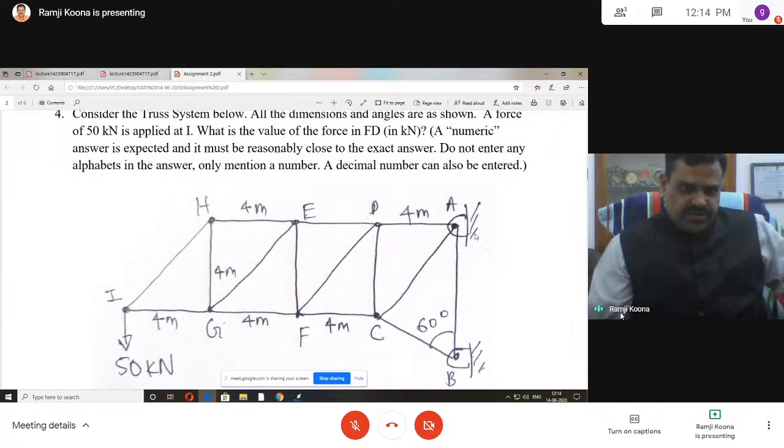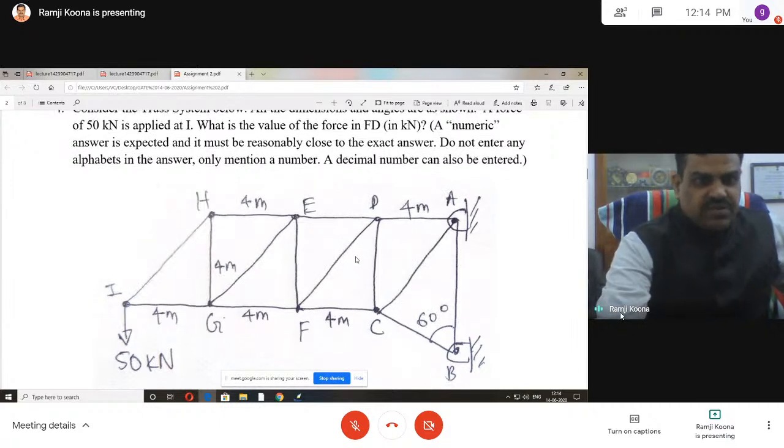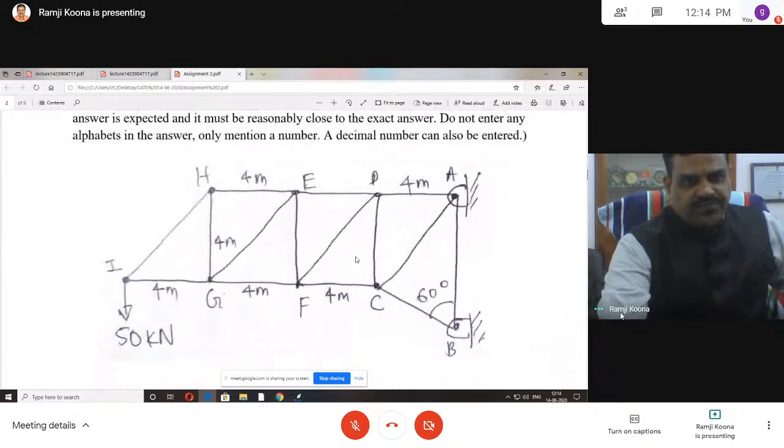No need of reaction forces if you take the left part. So for the left part, this is the section. Find out directly the force along the member. Like that, in GATE, if this method of sections applies, this type of structure is better.